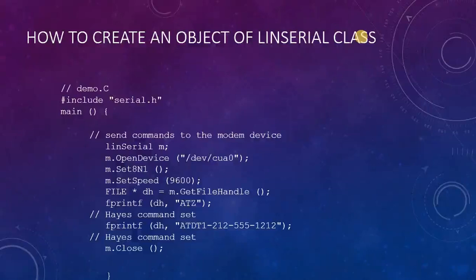I mean RS232 port. So the RS232 port is a file called /dev/cua0. Sometimes they are also called /dev/ttyS0. So now it is like COM1 in Windows, and you can create an object called serial. Then you can set all the parameters of the speed, protocol, everything.